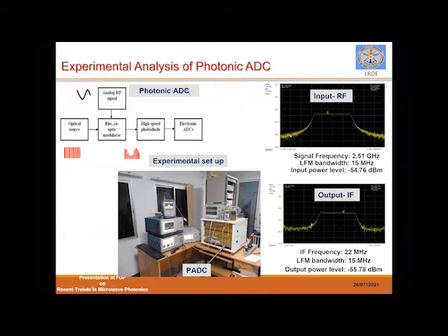When the signal is coming, that goes as the input to this, and then we will be feeding the MLL pulses as optical sampling clocks, and this will be used for sampling the received echo signal. And finally, the received echo signal can be converted to the electrical domain by using a photodiode or RF receiver.